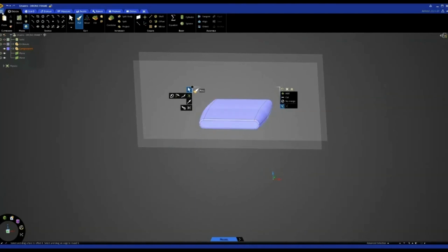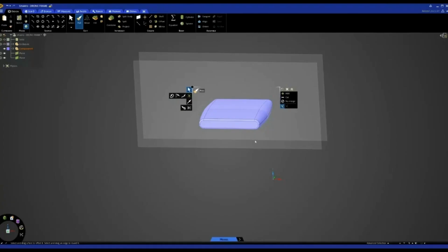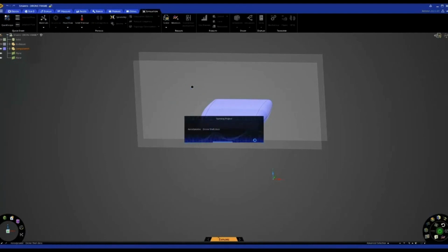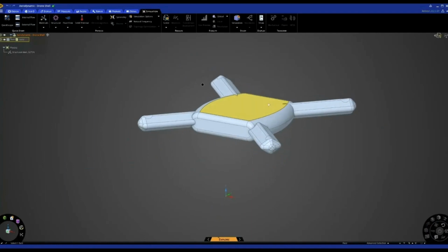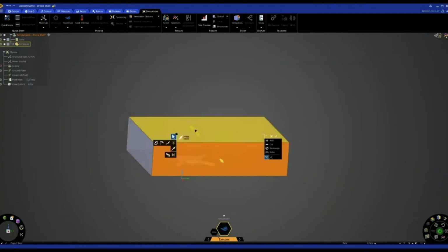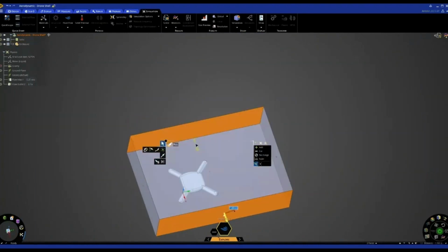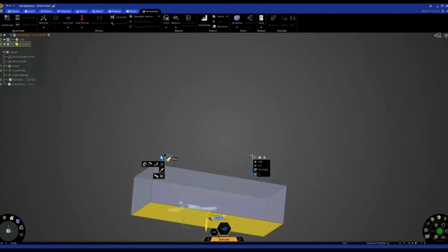But what I'll do is I'll open up the finished model, which is our more aerodynamic shape, and let's just run a quick simulation on that just to show the results on a more potentially aerodynamic shape of our drone skeleton. So exactly the same setup. We go into external flow, choose our inlet, choose our ground plane. As I did previously, you can modify this fluid zone. You can go a bit smaller. Let's just make that ground plane off the body.